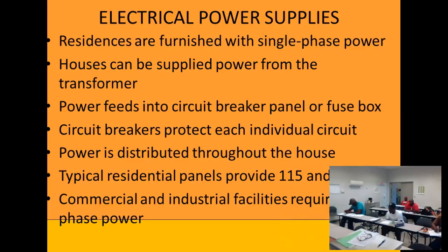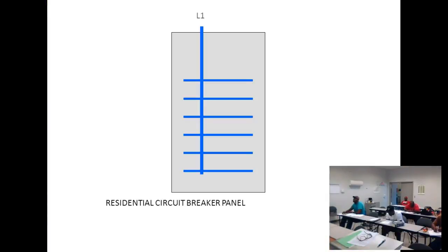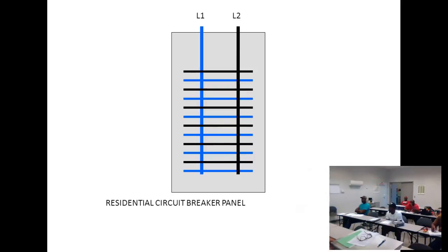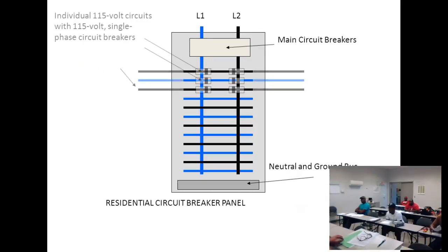Now when we look at this, and we'll look at this circuit breaker out here in just a second. Y'all seen this one out here that's not wired up, right? Remember, we got 2 hots coming in. Although we're calling it single phase, we got 2 hots coming in, and they're overlaid, and a breaker would stretch across both of them.